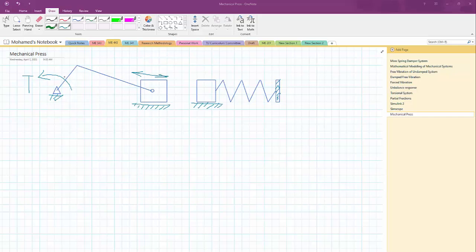moves due to the effect of the input motion, the piston is going to contact this specimen, and as it pushes the specimen, in real life it will be something like bending, piercing or stamping. The way we are going to model the resistance is using this spring. The way we are going to model the contact between the specimen and the tool is using a contact force element. We will drive the crank with a motion, so we'll learn how to define a motion in our system.